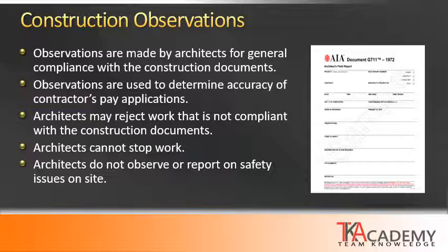Also important to note is that architects do not observe or report on safety issues on site. Safety is the sole responsibility of the contractor, and typically there is a site safety manager or a site superintendent who is responsible for safety. So obviously if there is an unsafe condition that an architect observes, they should simply notify the site safety manager or site superintendent and let them handle that within their own authority, and they should not include that in their reporting.